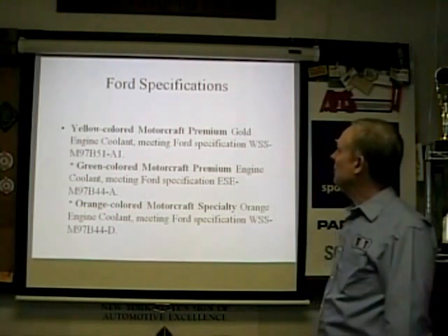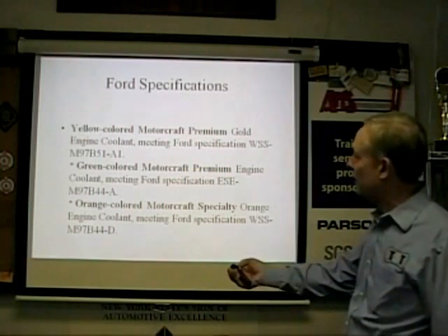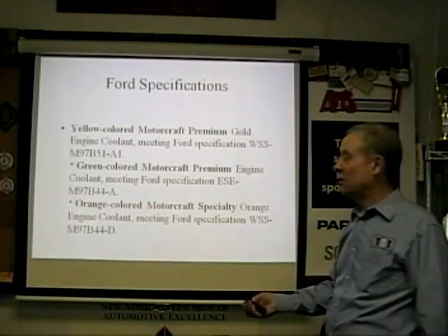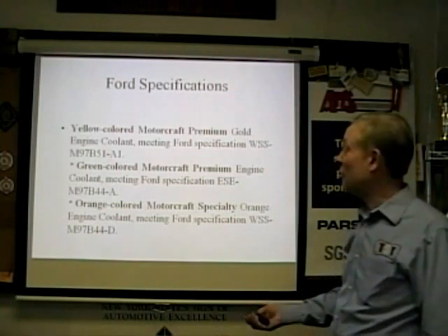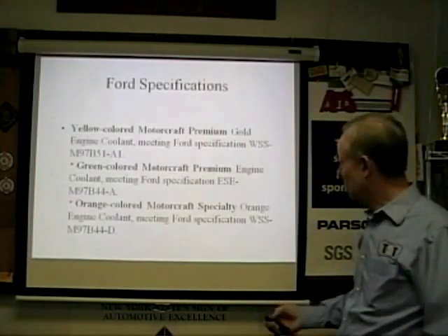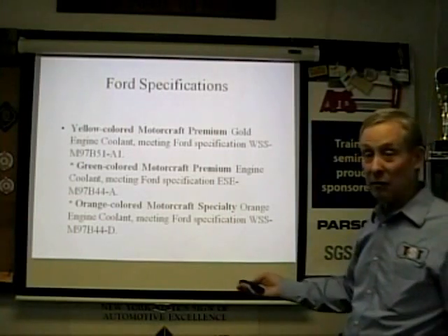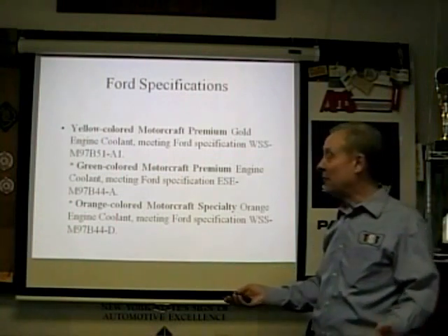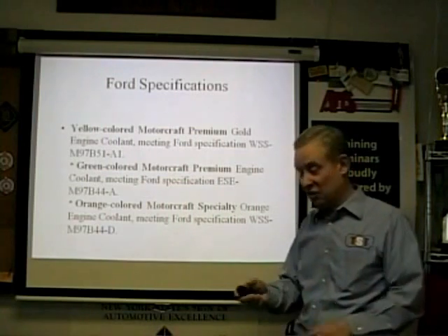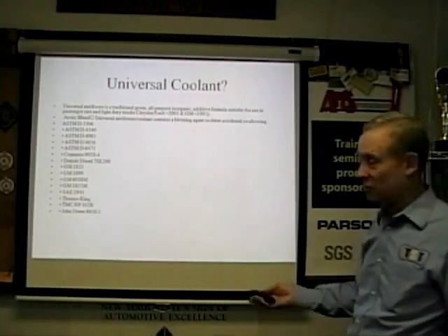Right. Ford specs. Yellow colored Motorcraft Premium Gold engine coolant meets this spec. You've got to read these specs. They have different engine families coming from different parts of the world nowadays. You've got to make sure you're using the coolant for the engine you have in your vehicle. So wow, one manufacturer with 3 different colors there. Yes, 3 different colors, 3 different specs, all Ford, because they're a global company. And they might have an Asian engine and a European engine or an engine that came out of Brazil, or it could have come from the US, it could come from anywhere. You have to read the specs. Again, just make sure it's for the vehicle you're working on.